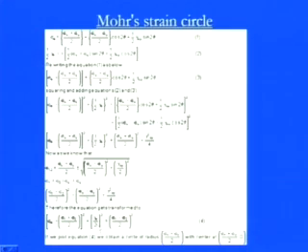So you see there is no component with gamma theta, there is a component with epsilon theta. So we can say this is the center point, because (x minus x1) plus (y minus y1) whole square will give you r square. So x1 comma y1 are the coordinates of the center. Similarly, for the circle equation, we can extract the information from that. So now we have two main important parameters to draw the Mohr strain circle. One is the radius, that is equal to epsilon 1 minus epsilon 2 by 2, and we have the center coordinate, that is epsilon 1 plus epsilon 2 by 2 in the x coordinate and 0 for the y coordinate, as far as the Mohr strain circle is concerned.